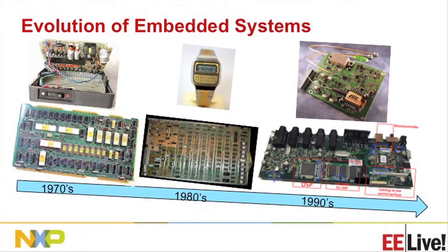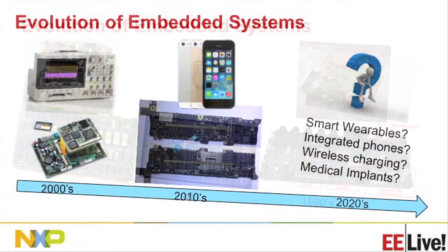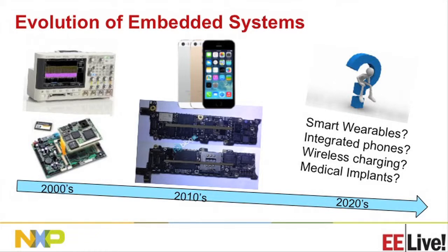So a bit of history about embedded systems. In the 70s, we had bigger boards. The popular packages were DIP. The trend continues into the 80s, where you would see the SO, SSOPs. Boards became slightly smaller. In the 1990s, the trend continues. TSSOP dominates. And these are like 16 pin or more packages on the board. So coming into 2000, the trend continues. You see more and more size shrinking, smaller systems there. The popular packages are becoming leadless packages, which are QFNs, thinner packages. And this is what we see in smartphones today.